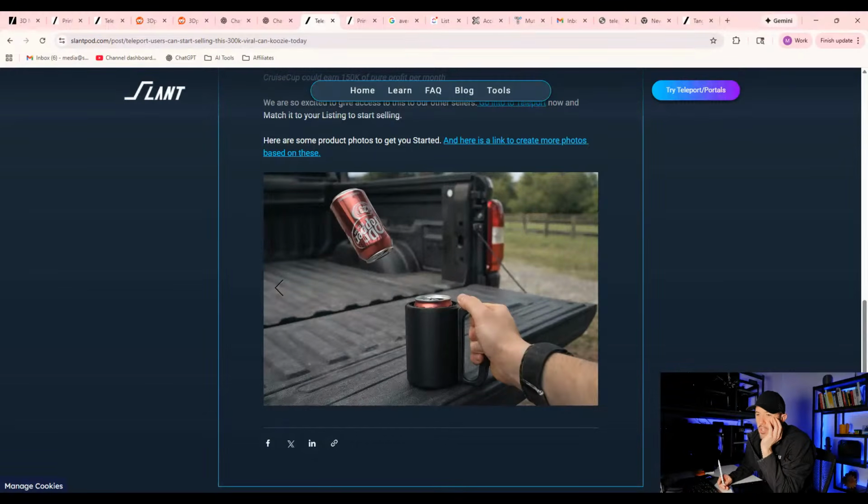Newbie question: what are your steps when you set up a new filament? How do you dial it in? It's fairly typical. We have some calibration prints, some baseline model prints of things like overhang, fit, tolerance, and so on. If we introduce a new material, we have to print those calibration prints and make sure all of them are coming out to spec. And we tweak the slicing settings for those parts until they come out to spec. And that's how we qualify a new material at any given time.